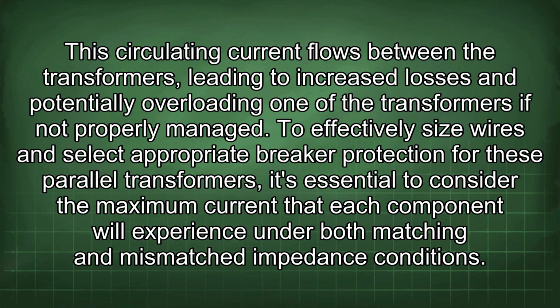This circulating current flows between the transformers, leading to increased losses and potentially overloading one of the transformers if not properly managed. To effectively size wires and select appropriate breaker protection for these parallel transformers, it's essential to consider the maximum current that each component will experience under both matching and mismatched impedance conditions.